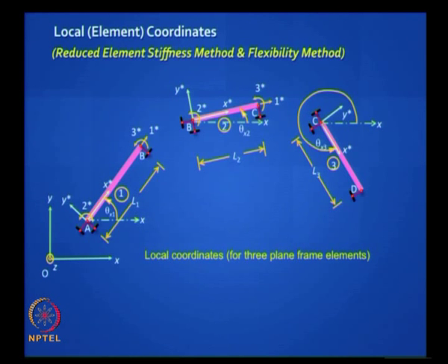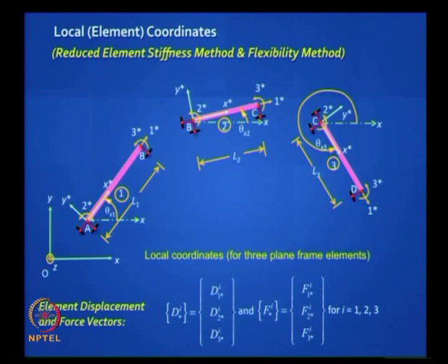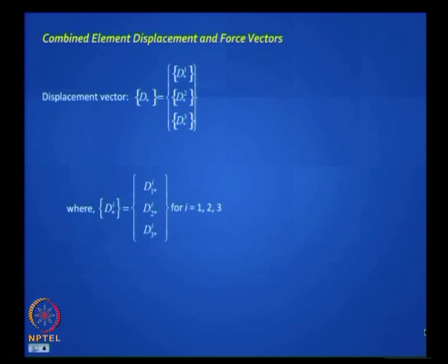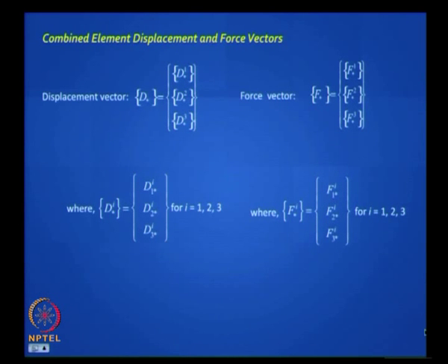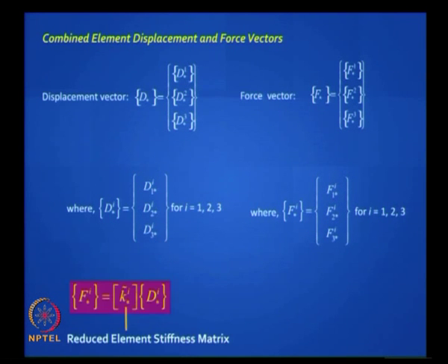So you have 1, 2, 3 everywhere, right. Does it make sense? Okay, these are my local coordinates. Now I can put it all together and I get my combined element stiffness. So for each of them it is like this, got it? That 6 became 3, that is all, much easier to handle, and there are 3 elements and I can put them all together and that is my combined element stiffness matrix. Does it make sense? Everything that we did till now except the size is dramatically reduced, and you put a tilde to make sure that you are clear.